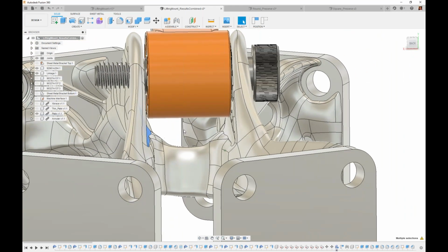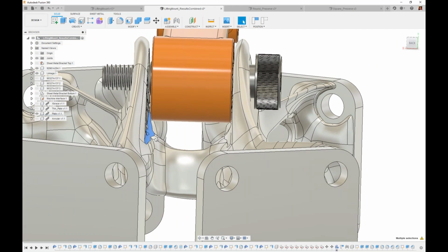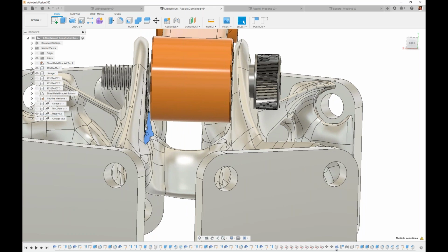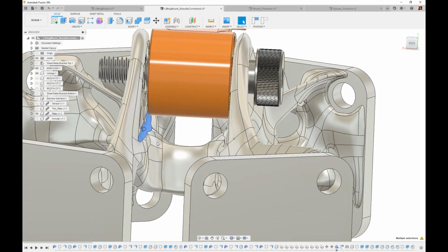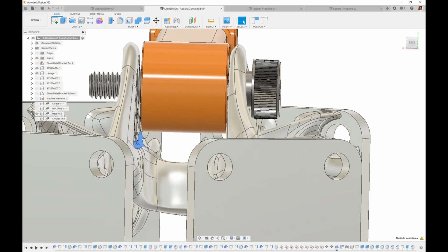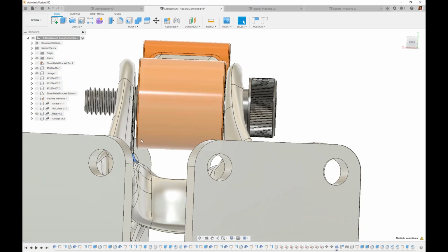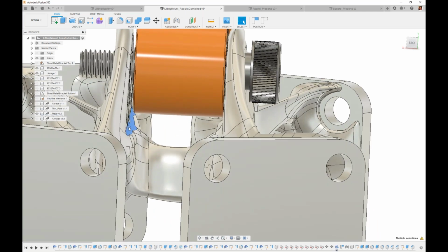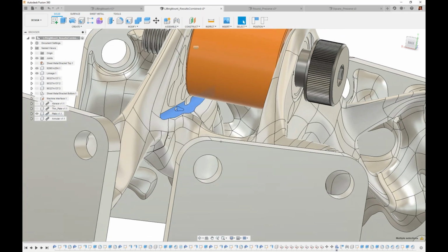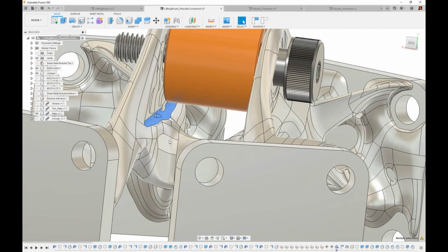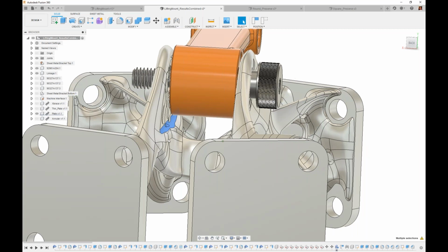That's the Boolean operation to make sure my preserve, or my obstacle region, is cut out from the organic shape. If I were to get rid of that round, I'd still clear my original part. It just wouldn't have that surfacing there, since my obstacle region was a little larger than it needed to be.